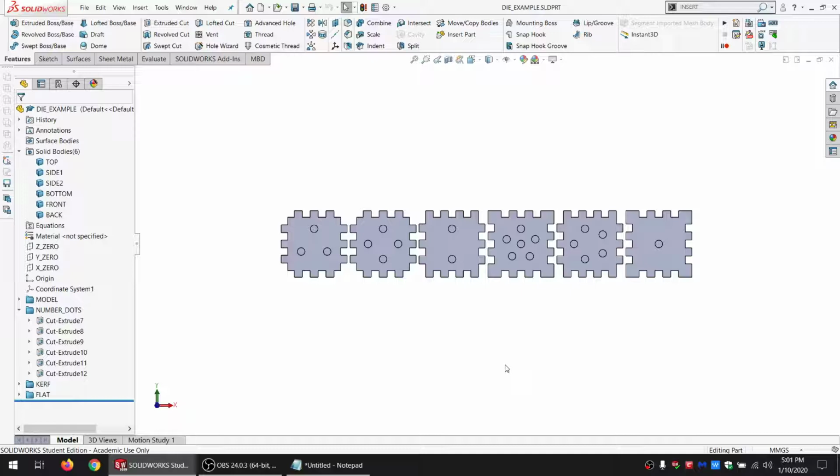And then we'd want to select all these circles and change them to a different color or a different cutting layer, depending on what your software uses, so that it's cutting these, but it's just engraving these, or it might even just be doing a really fast cut around the outside just so you've got a basic circle. So I am going to go ahead and cut this out, or I'm going to set this up, cut it out, and